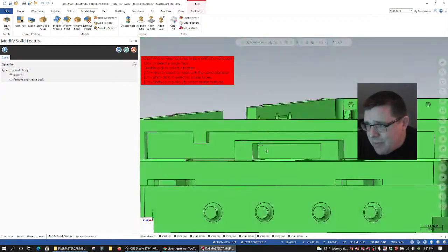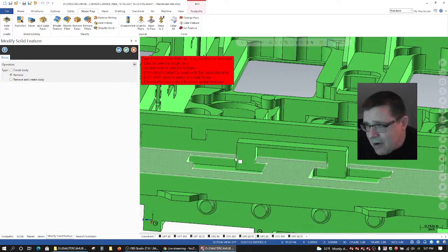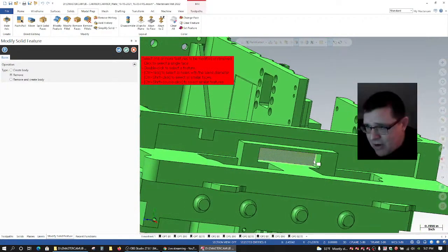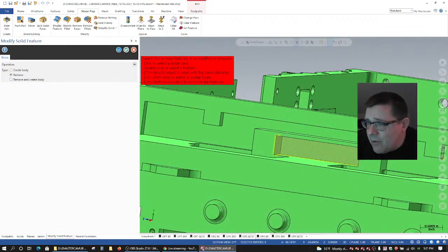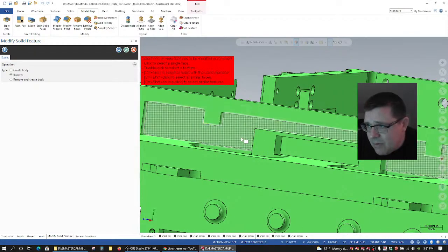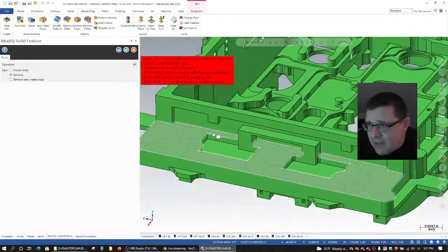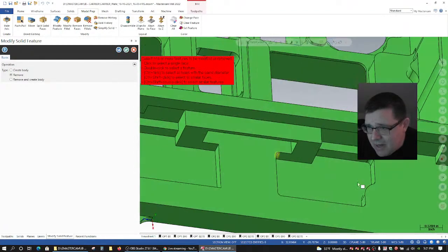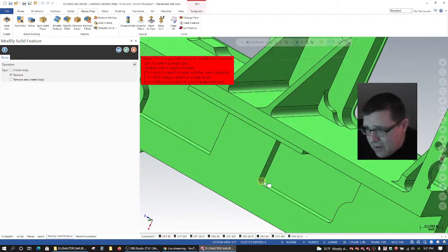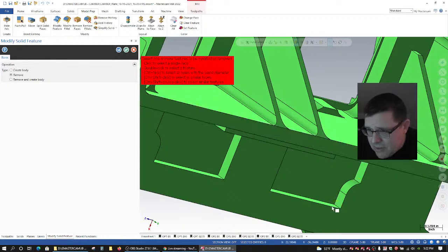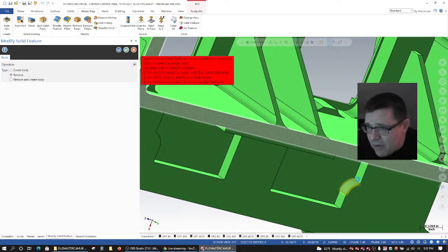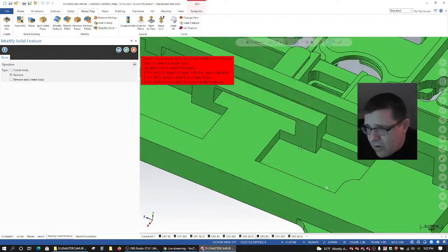So in order to remove something like this, I've got something weird because I got a face out here, right? But if I try the 3 inner surfaces plus this guy, it may be able to now treat that as a pocket. Nope. Okay, so if that doesn't work, it could be that I still have too many little intersecting fillets. So we'll try getting rid of these first. You can also try getting rid of these little guys to see if that's treating it like a corner. Nope.